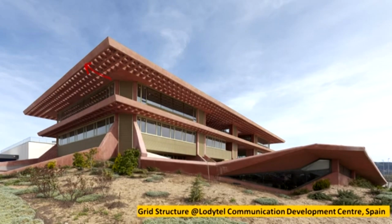So, this is the advantage of the waffle slab: the building can be of a rectangular shape, it can be of some curved shape, but this will help to distribute the load effectively, and at the same time it will reduce the amount of material from the section. It is an improvement of the section, and it can also be used for a large span.